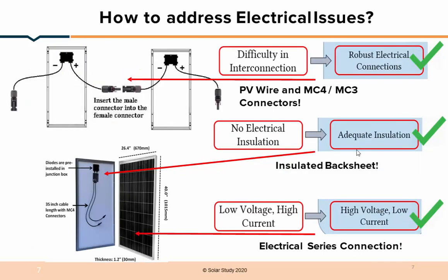Now we have to see how we can connect to the electrical system. As we know, a solar cell contains two aluminum or silver strips, which are very delicate. So if I connect those directly to an electrical system, there is a chance of breaking. So what the industry did is connect all the negative terminals in a single bus and all the positive terminals in a single bus.